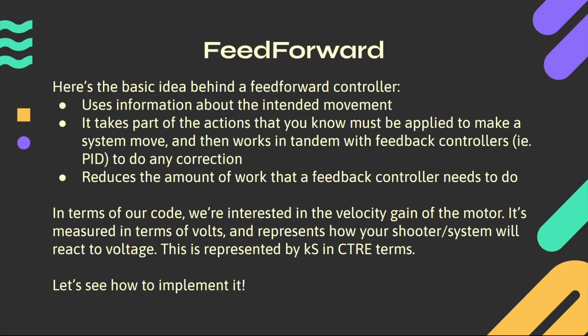Before we get into the code, the main thing I want to mention is feed forward is kind of like the kick that you give to your system in order to get it moving. That's how I initially viewed it, but the main purpose behind feed forward control is that we want to take what we know about the intended movement of our system, and then have it work in tandem with PID to do any correction.